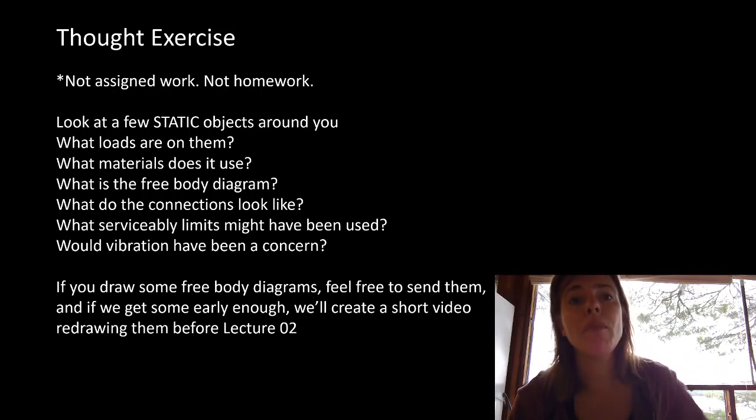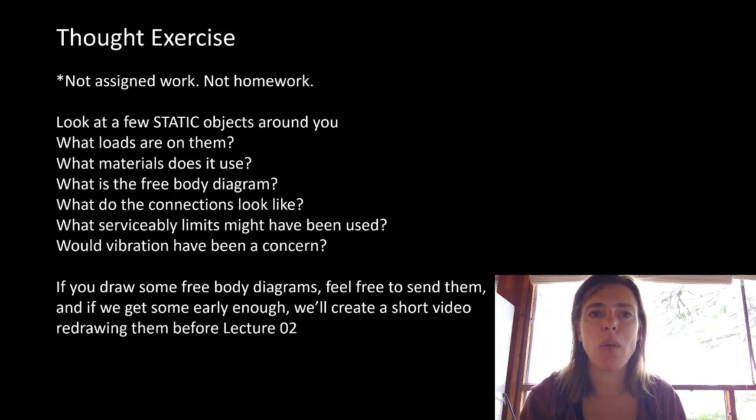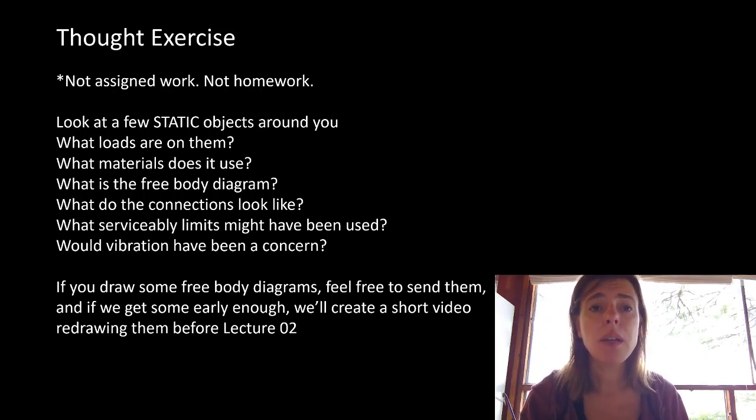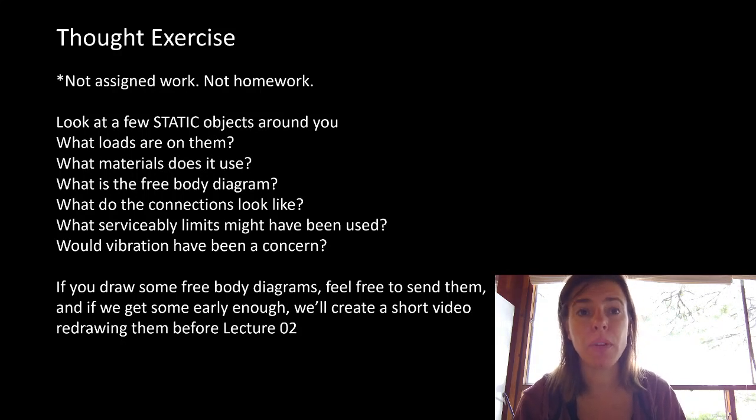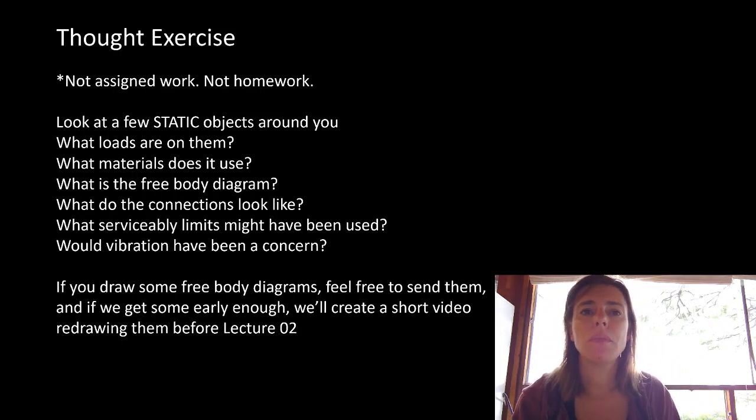Can you imagine where all the reactions are for it? Can you imagine where all the loads are being applied to it? What do you think its connections look like? Where is it connected? How is it connected? Would you think that was a moment connection or just a pinned connection? Remember, a pin can't transfer moment, but a moment connection can obviously transfer moment. What serviceability limits, if any, might have been used in the design of that? And do we think vibration might have been a concern?